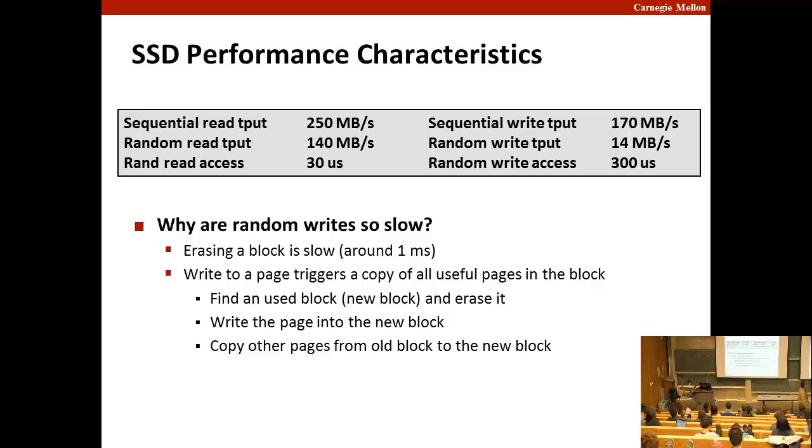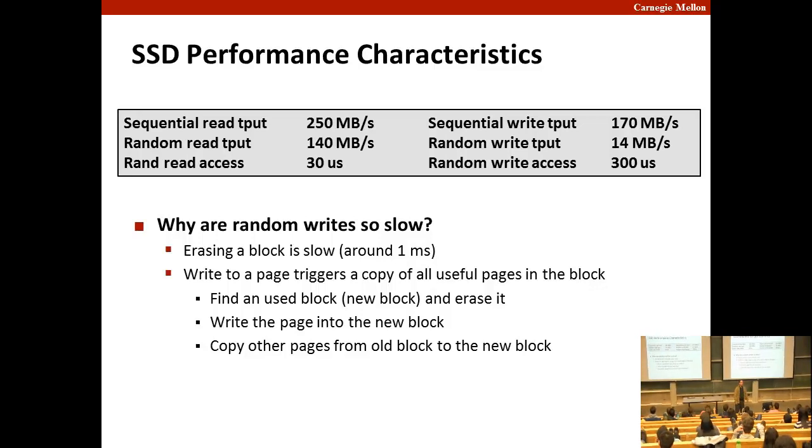Okay. But the reason that writes were initially slow is because you couldn't really update a flash memory. You had to zero the flash memory and then rewrite the whole thing. So any write involved first a read, then a write. Read to find out the old bits, merge in the changes, write out the new bits. And so it was read, erase, merge, write. And that was just a slower process.